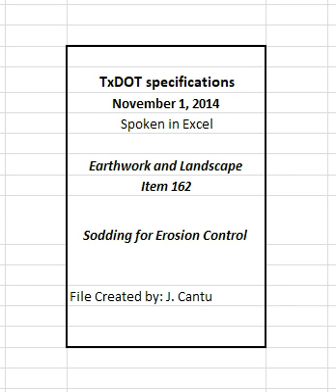Place sod so that the root system will be completely covered by the soil. Firm all sides of the sod with the soil without covering the sod with soil.